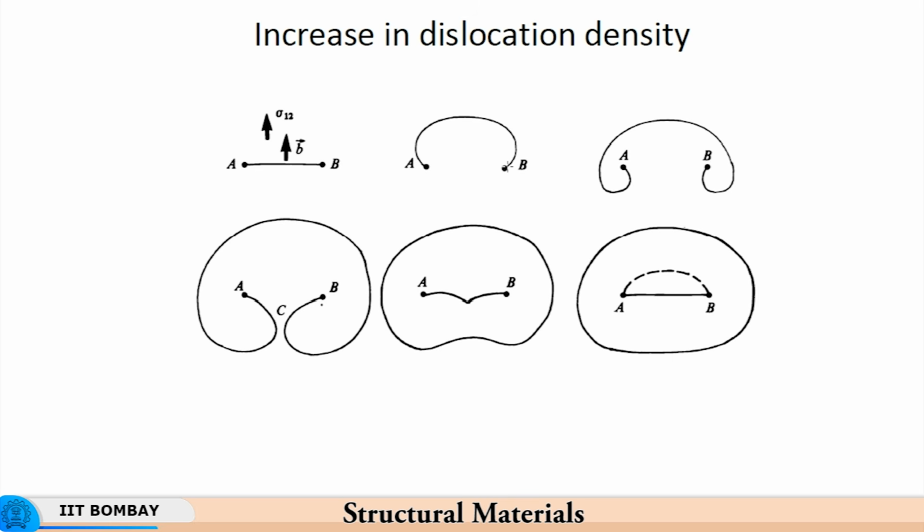We will see these details much later, but that is the reason why we are looking at dislocation multiplication. Once the dislocation starts moving, it doesn't stop with just the movement of dislocations. The dislocations multiply as they move, so if you start with x number of dislocations, the number can go to 10x after a certain amount of deformation, a certain amount of strain.